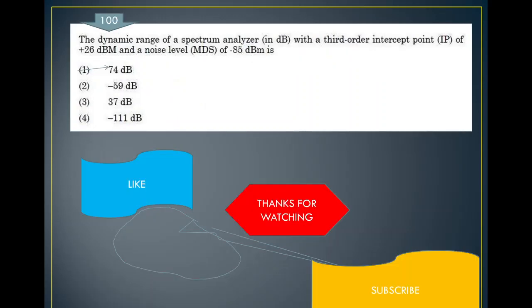Next, the dynamic range of the spectrum analyzer in decibels, with the third order intercept point IP of plus 26 dBm and the noise level MDS of minus 85 dBm, is first 74 dB, second minus 59 dB, third 37 dB, and fourth minus 111 dB. The correct answer is 74 dB.